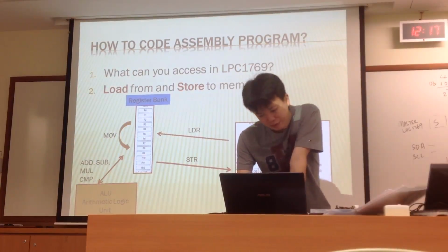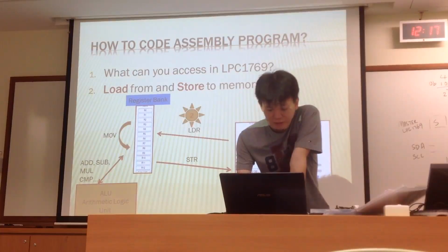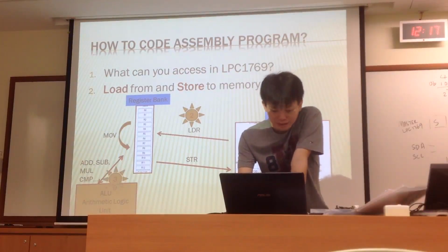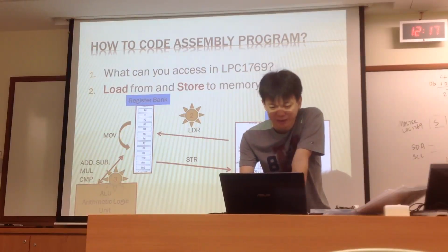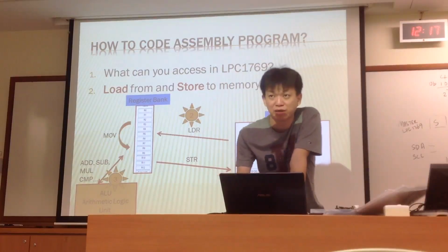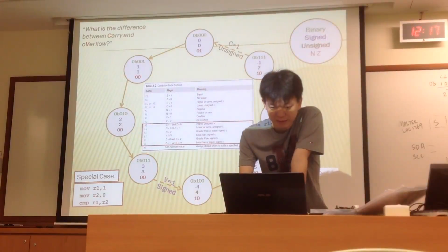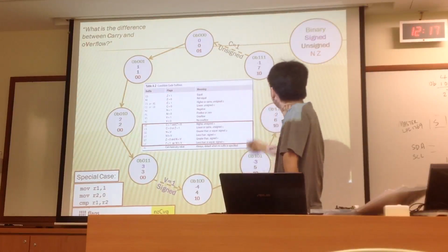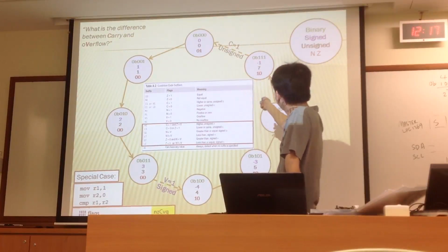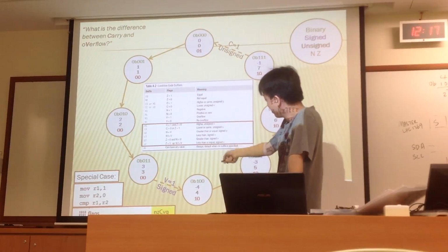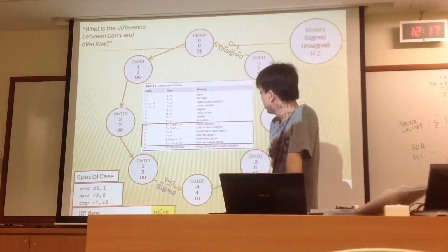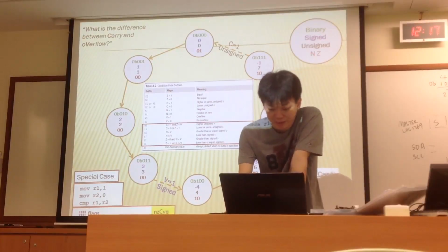So normally the first step you don't need to worry about. You need to know how to load the data and how to do all the algorithm calculation. Normally the questions are quite simple. For the mathematics part, they just give you an equation and you write it accordingly. Same thing for carry and overflow. Just remember carry is triggered whenever you cross this line. Whenever you cross this line, you trigger an overflow for signed numbers.